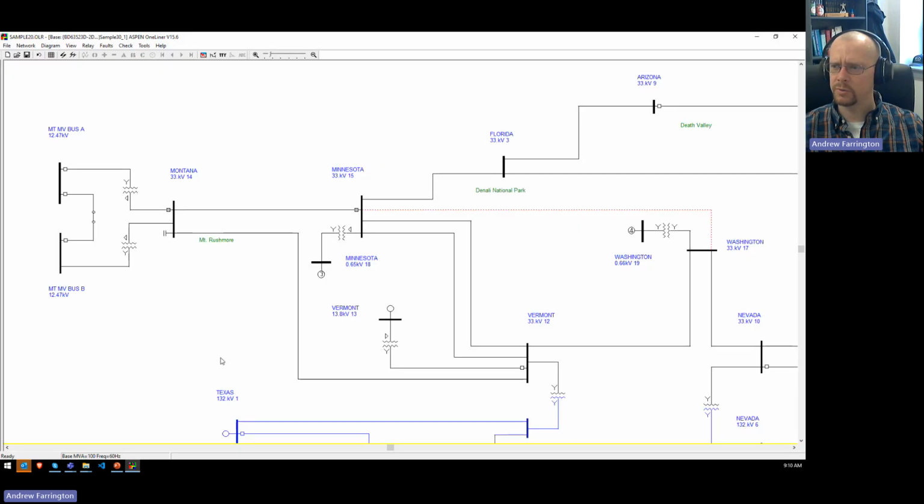One other thing to note about that is the relay group, the forward direction is towards the line or transformer, and the reverse direction is towards the bus. And that's intuitive in most situations. But sometimes you might have a relay that has a CT that's wired with the reverse polarity. So for that relay, forward is towards the bus and reverse is towards the line.